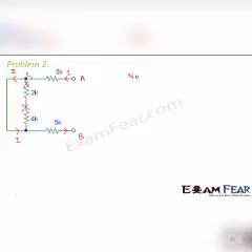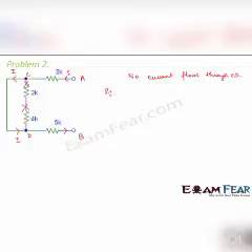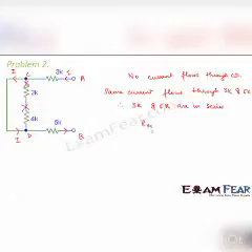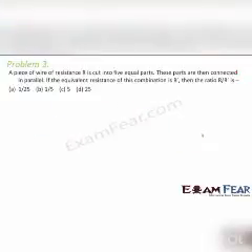From here we can see that, let us call this CD. No current flows through CD, and we also see that the same current flows through 3K and 5K. Therefore 3 kilo ohms and 5 kilo ohms are in series. So what would be the equivalent resistance? That will be equal to 3K plus 5K, that is equal to 8K. So this would be the equivalent resistance of this combination. Let us look at problem number 3.